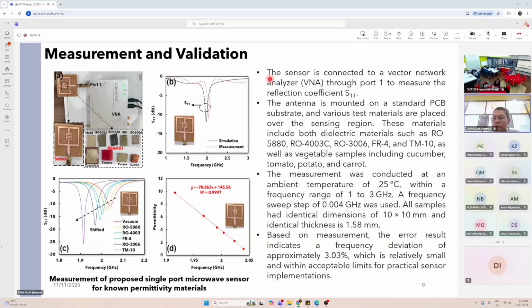We don't need the resonator's reflection coefficient to be below -10 dB. It's okay if you simulate and only get -5 dB or -6 dB. The main important thing is that if we put the sample, the resonant frequency moves lower, so we can assume that the resonator can be used as a microwave sensor. I think that's all from me.